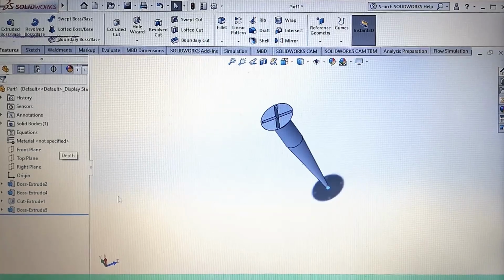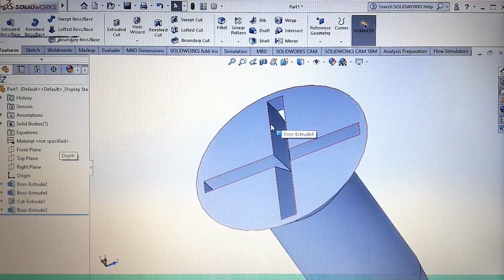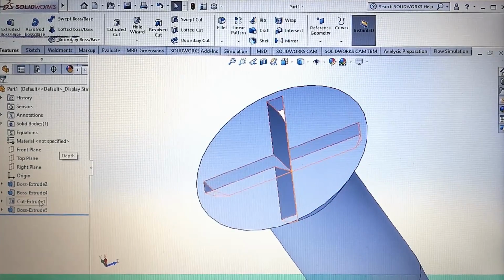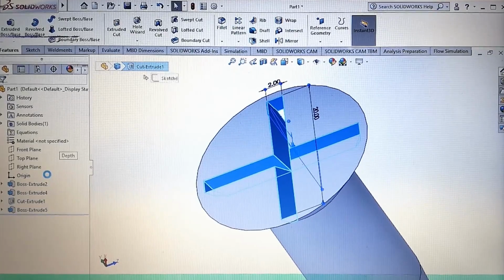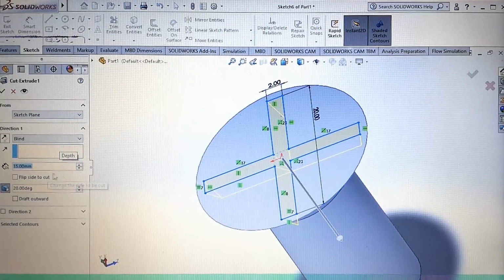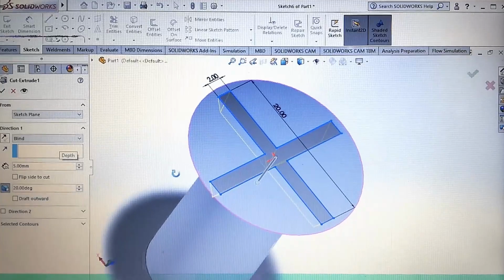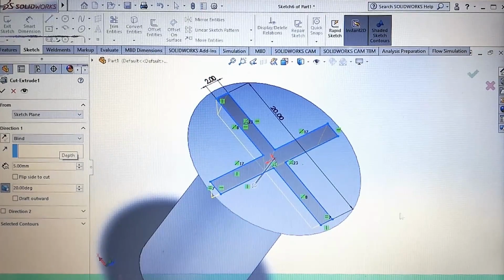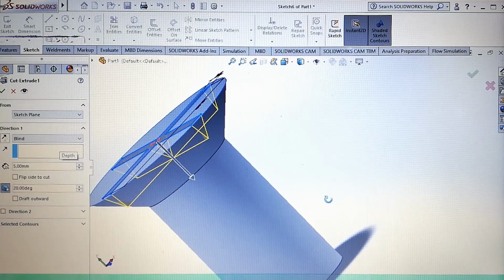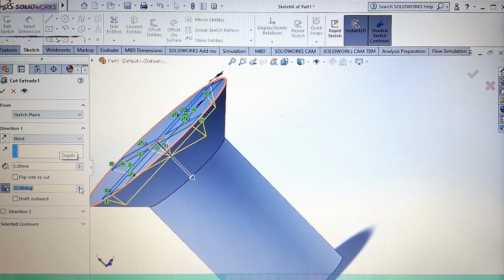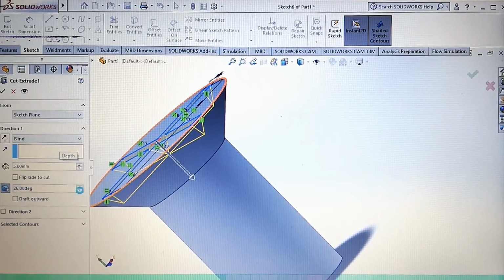And what we have done here, that extrude cut material, the depth is a little more, so we have to reduce this one. So we'll go back to extrude cut, features, edit features. The length was 15 mm. We'll make this one 5 mm. And we'll make the angle a little more, in which the depth of cut becomes a little less. Angle 25 degree. Okay, done.